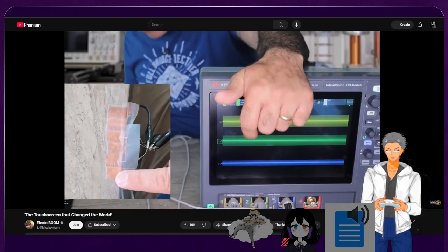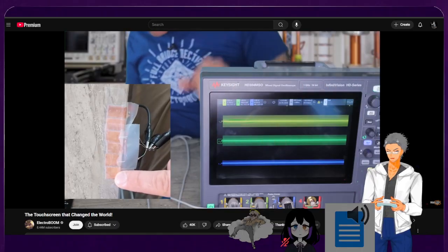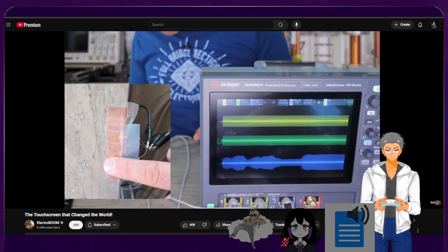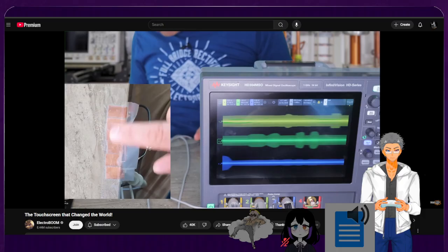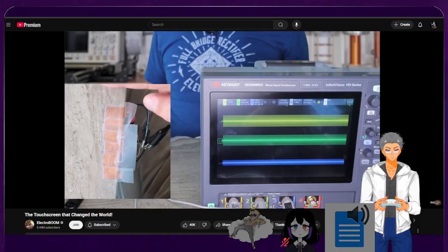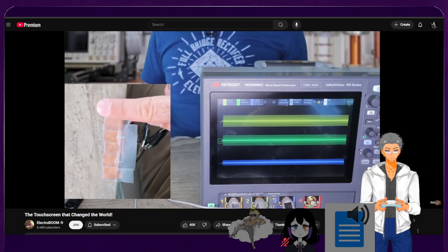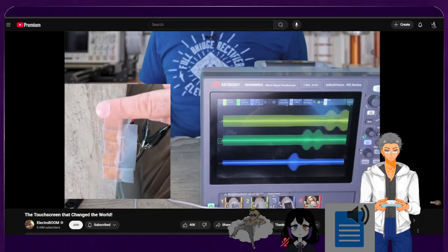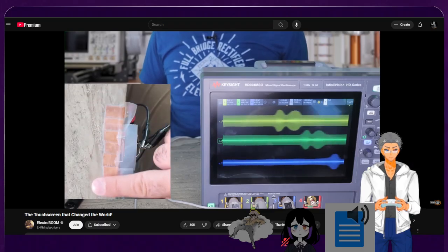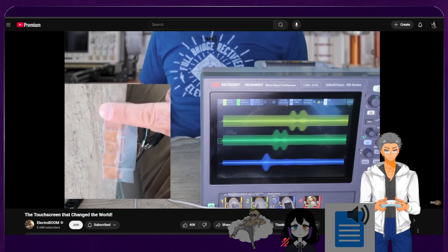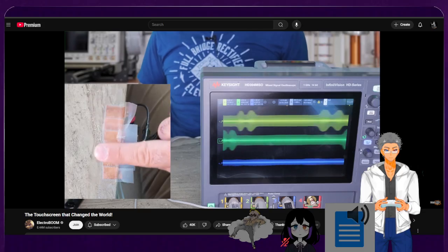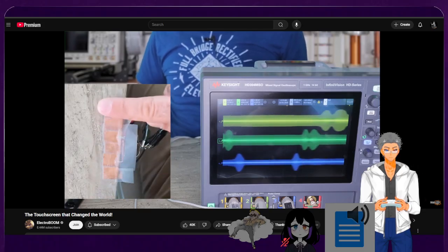You can see the signal on the bottom channel is half the other 2 because its pad only has 1 signal pad beside it, compared to the other 2 that have 2 beside them. And for the same reason, as I pass my finger over these pads, you see double bumps on 2 of them, which is fine. I mean, if these pads were much smaller compared to my fingertip, the double bumps would combine into 1. But hey, we are sensing.